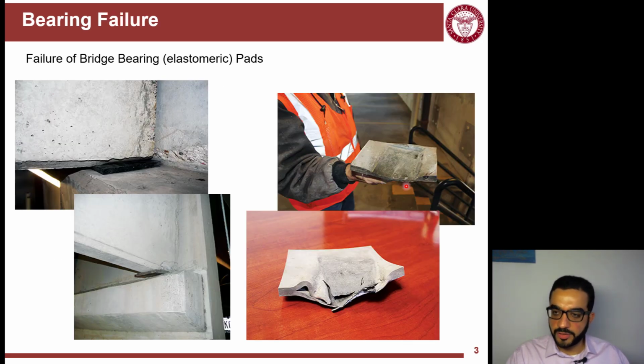So we'll see a couple of practical examples of bearing stress. The famous one is in bridge design and construction. In this photo, this is a beam of a bridge that's carried by a pier of the bridge. When we design this beam, we design it as a roller connection. So we allow the beam to roll, but we cannot make it roll on these two hard surfaces. So we put elastomeric pads here, a special material that will absorb that load and allow the sliding of the member. Over time, these pads deteriorate and get crushed by the beam loads. So that's one example of bearing failure.